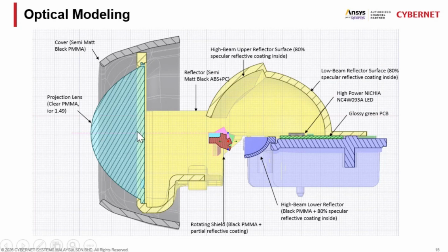After we import, for this projection lens and also this reflector, we can use the Radiance simulator, which I just introduced, inside the optical part design. In this OPD, we can directly put in all the parameters so it can generate directly based on this shape. We can include it into our CAD and put in the actual coordinates. After this, you can see all the materials are mentioned here, so we can input all the materials and set the material into our geometry for the optical properties definition.